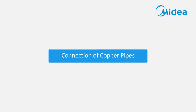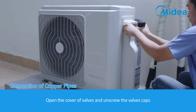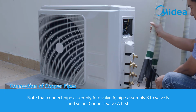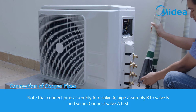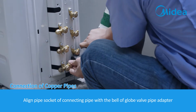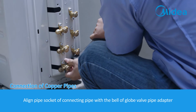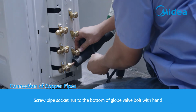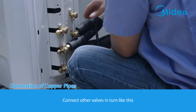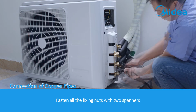Connection of copper pipes. Open the cover of valves and unscrew the valve caps. Note that connect pipe assembly A to valve A, pipe assembly B to valve B, and so on. Connect valve A first. Align pipe socket of connecting pipe with the bell of globe valve pipe adapter. Screw pipe socket nut to the bottom of globe valve bolt with hand. Connect other valves in turn like this. Fasten all the fixing nuts with 2 spanners.